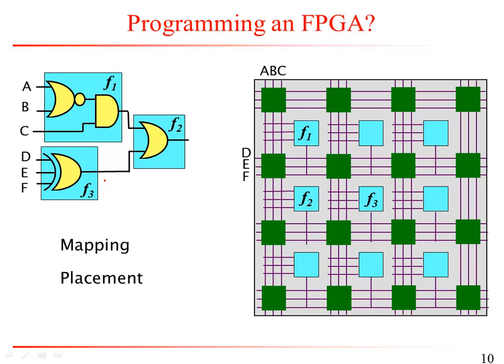Something similar to what you did in ASIC would happen here, but it has its own specialized algorithms, and you have to worry about the discrete structure of the routing and so on. But I'll talk about them in a later recorded lecture when I talk about FPGA CAD. So once you decide on the placement, then you have to worry about the routing, and the routing could be done using Dijkstra's method, or similar techniques that we learned in 5301.